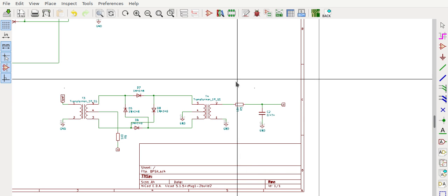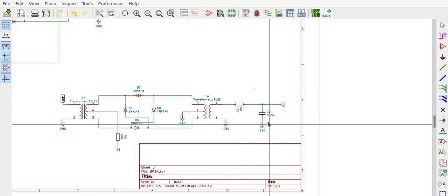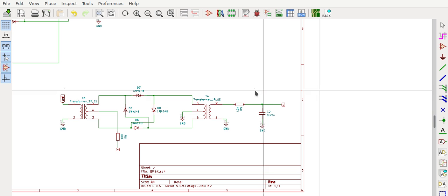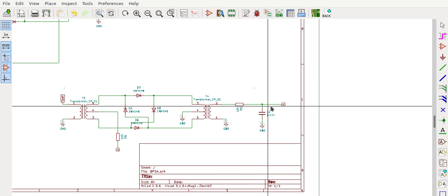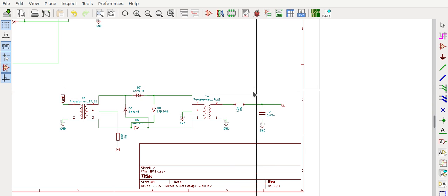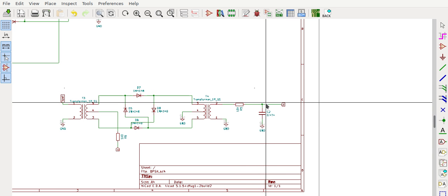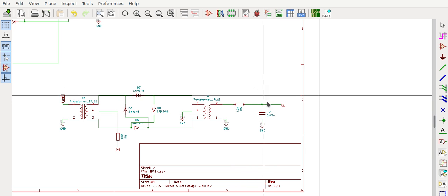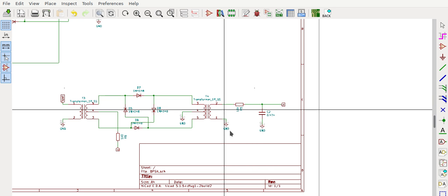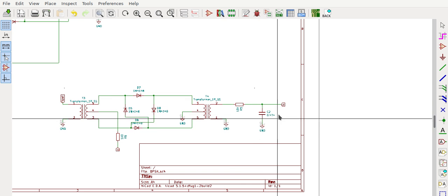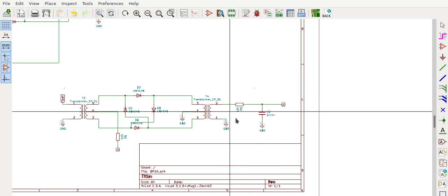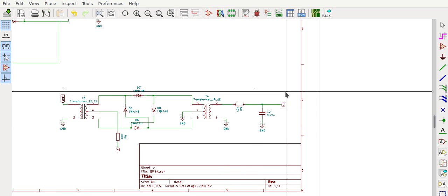So we have to use a low pass filter itself. You can use a higher order filter using LC circuits, but what I am using for simplicity here is a first order RC filter, and the design of this filter will be pretty easy. You have to accept anything below 10 kilohertz and reject signals above 10 kilohertz.